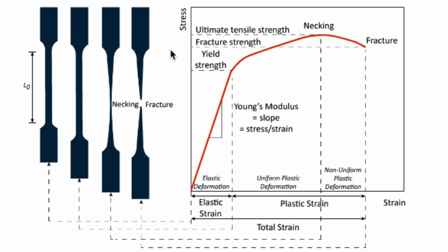without appreciable plastic flow. These microstructural rearrangements associated with plastic flow are usually not reversed when the load is removed, so the proportional limit is often the same as, or at least close to, the material's elastic limit. Elasticity is the property of complete and immediate recovery from an imposed displacement on release of the load, and the elastic limit is the value of stress at which the material experiences a permanent residual strain that is not lost